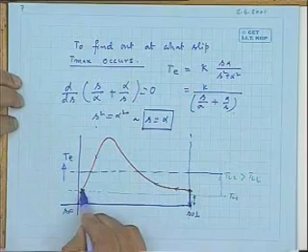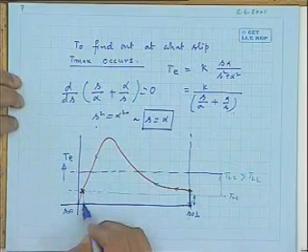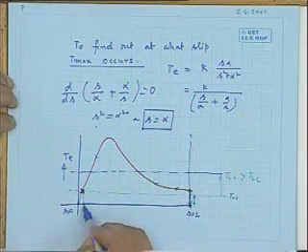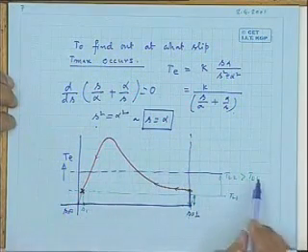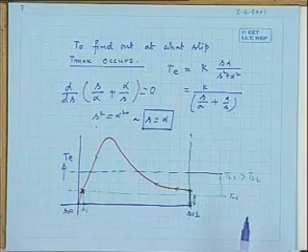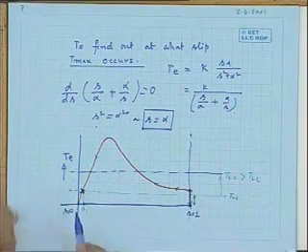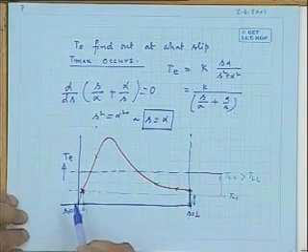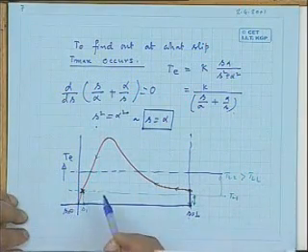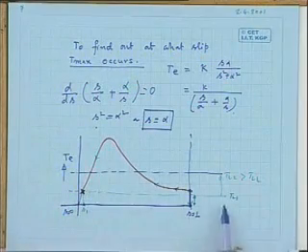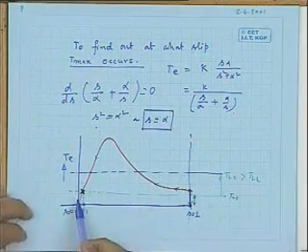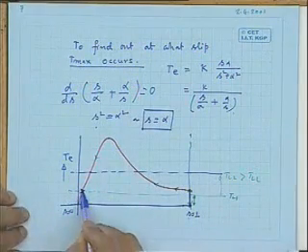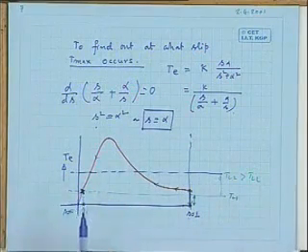Suppose you increase to TL2, this level. The machine was operating here. Let us explain. The machine was operating steadily at this point, running at a speed decided by this S1. Now suddenly the load torque on the shaft of the machine is increased. Speed, can it change instantaneously? No. So right at that time, that is t equal to 0 plus, when at t equal to 0 you have increased this load torque, how much is the electromagnetic torque developed by the machine?